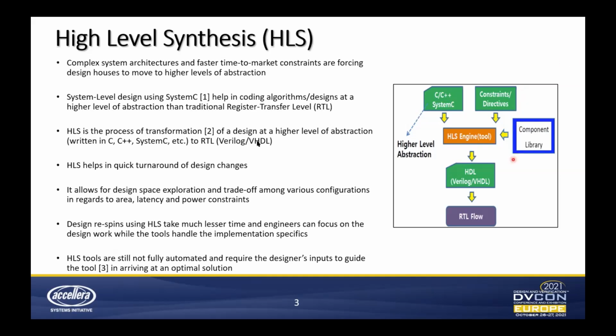The figure depicted here is the typical HLS flow. The SystemC design, as in our case, along with a process node technology component library and constraints and directives, like what the area should be, what the latency should be, and what power constraints should be, are some of the inputs given to the HLS engine.